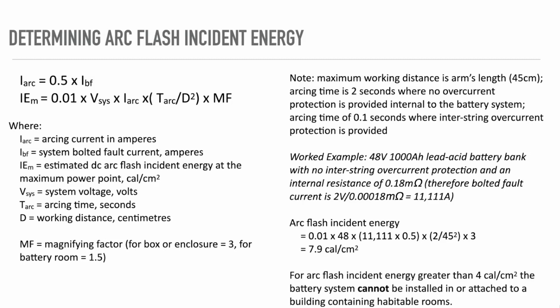You shall calculate the arc flash incident energy, and it has to go in part of the recommendation or requirements for PPE. And we'll talk about PPE based on cal level in a minute. It looks a little bit complicated at first, but after all, it's really just multiply, divide, and there is a square in there. So you can do it on your phone or your pocket calculator.